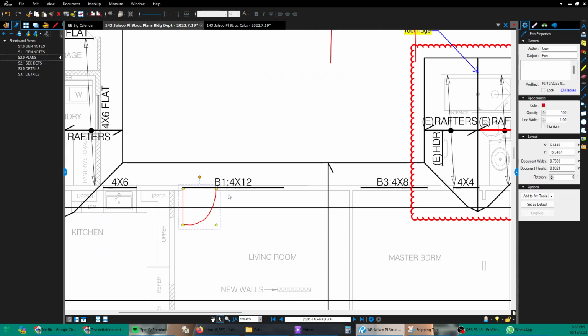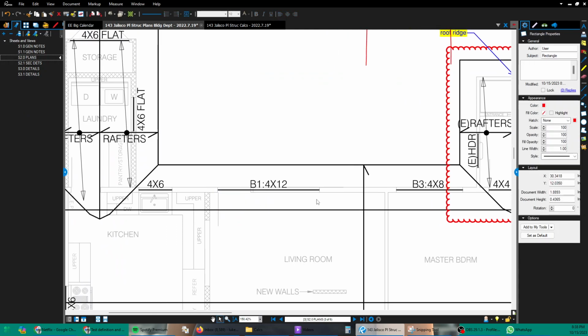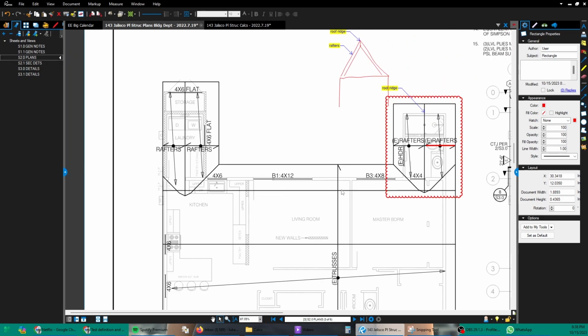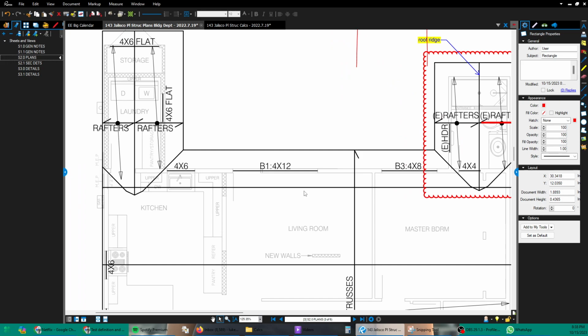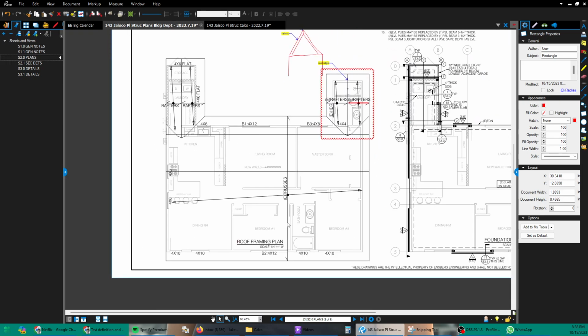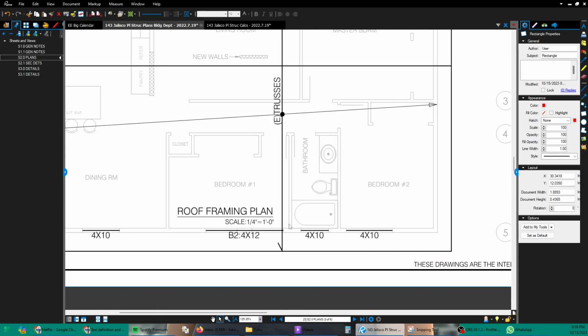Even though beam grading does exist, it's not a perfect science. It's often done by eye, just by people looking at pieces of wood and deciding what grade they should have. There could be a small crack in a beam that nobody saw. So we don't want to design things up to 99% capacity. Usually 95% or less would be good, or 90%.